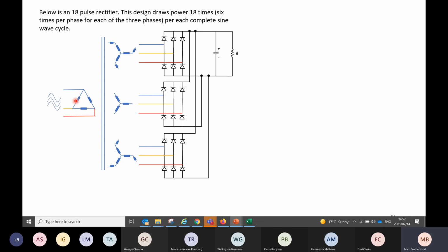And as you can see here, this would be a slightly different design on my transformer. This is a delta transformer. You'll see there's no neutral here. Okay, there's no neutral on the delta. It will go through the windings. And then here we're going to star the network. So this will be my sort of in phase, and here I'm going to phase shift a few degrees, and you'll see there we're phasing up and here we're phasing down.